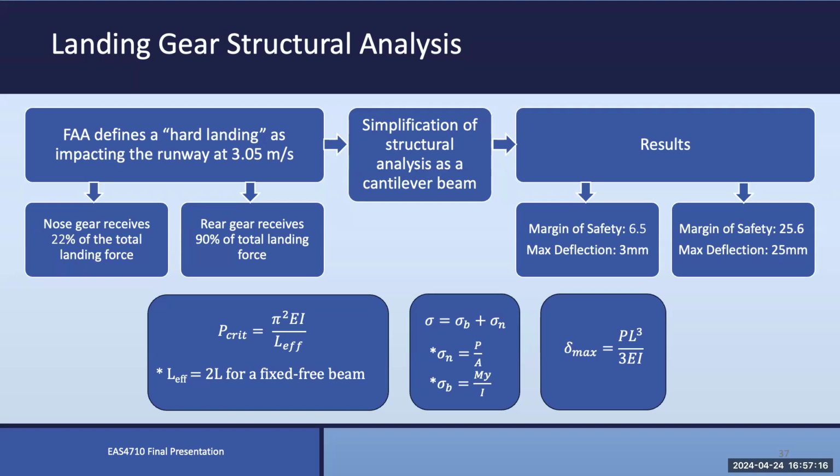So you said you had the plane instrumented, right? It sounded like you had it instrumented for flight. Yeah, we had a flight controller, and it included a gyro compass, a LiDAR, and additional capabilities within it. Were you taking acceleration measurements there? Yes, the FPV camera showed the G-forces as the plane was maneuvering as it took off, and we captured the 3.6 Gs that we were able to capture at maximum during the flight. And that's where we got that number from.